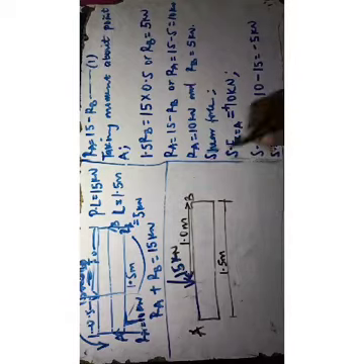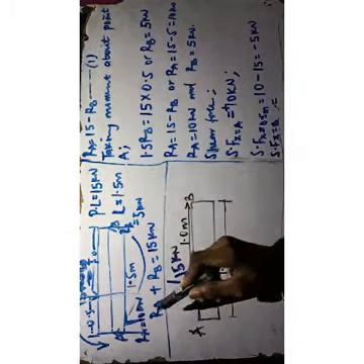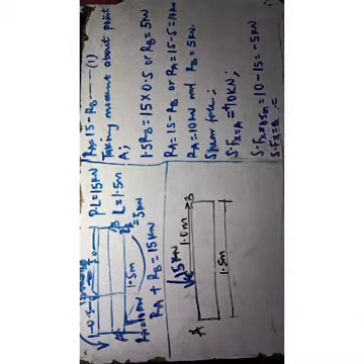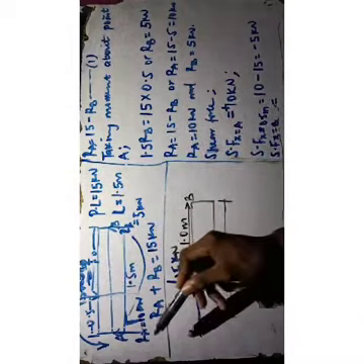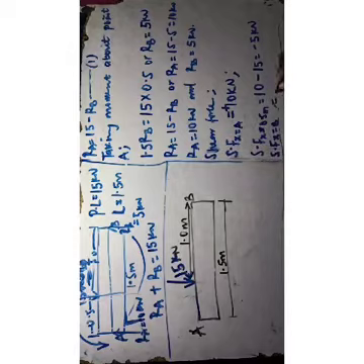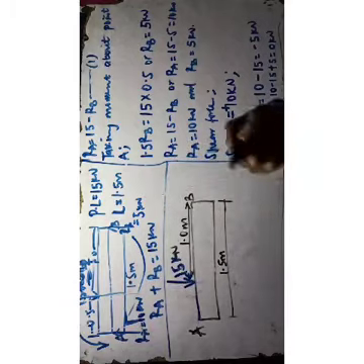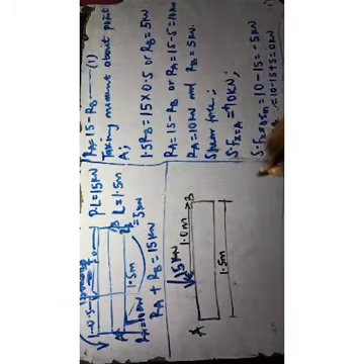If I cut it here, that will be 10 minus 15 plus 5. That will be equal to 0 kilonewton. Or if you want the shear force to be 5, you should remember when you want to halve it, that will be equal to the shear force there. So that's the shear force here.